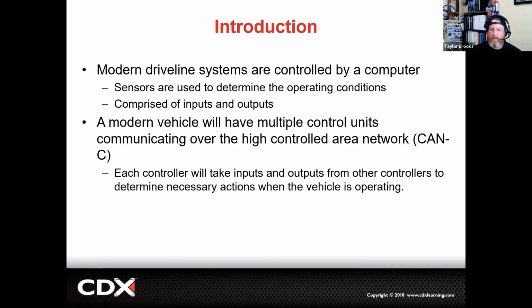All modern vehicles within the last 25, close to 30 years now, are operating on controller area networks, otherwise known as CAN systems. Drivetrain components, much like the engine and occupant safety components, all fall under the CAN C or chassis communication leg of the vehicle system. Now, this is the fastest regulated controller area network. What I mean by regulated is that CAN C is regulated by OBD2.